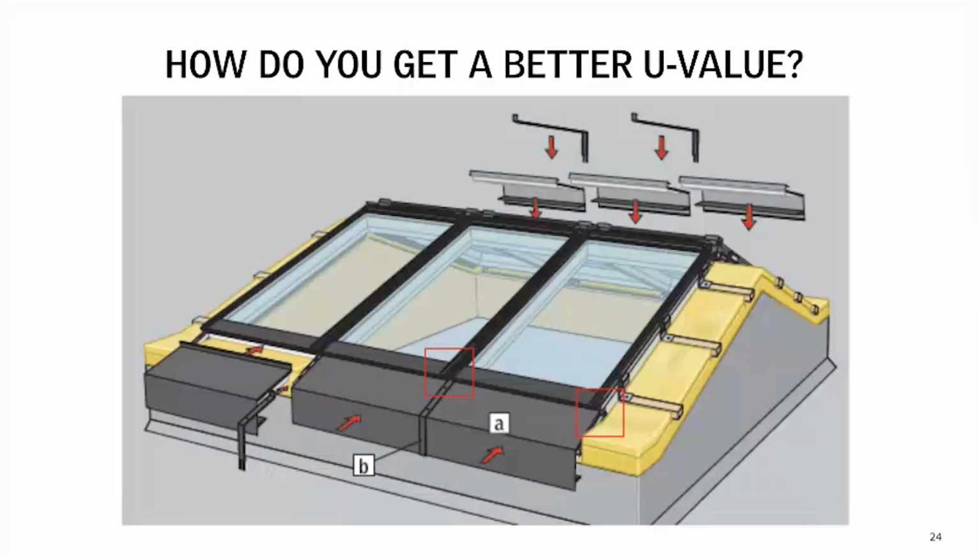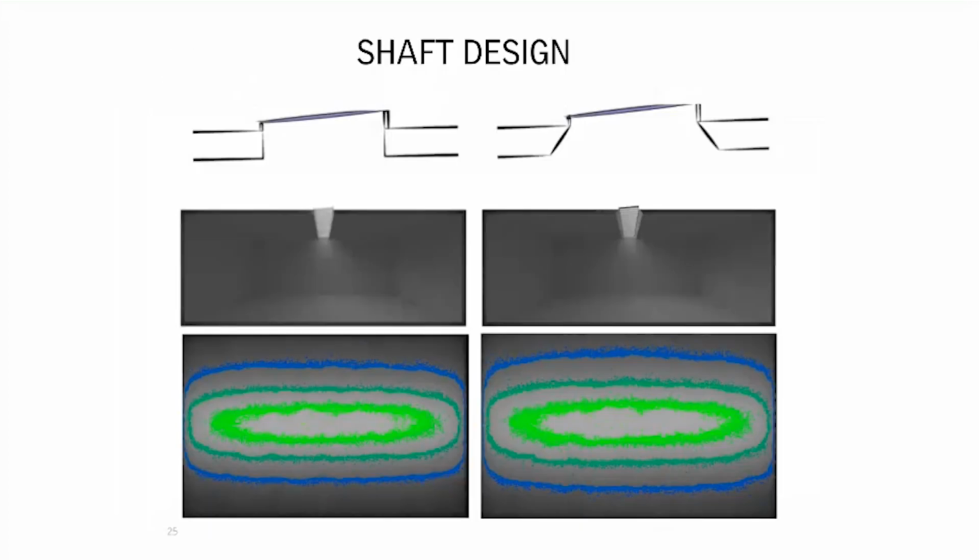Now, how you integrate into the building does not count as part of the U value, but when you're looking holistically at the energy performance of a building, you have to factor this in. Now, on sloped roofs, you could integrate the skylight or inset the skylight slightly into the roof. And we do this to some extent with some of our residential products going on sloped roofs. But if you're doing commercial projects and you're going to be operating on a flat roof, you likely have to lift your skylights up off the roof to get them out of the snow and watershed situation at that location. So you're going to have what we call a curb. A curb is the structure that the skylights are going to sit on. So to have a high performance system, we should be looking at how do we insulate that curb to make it better for energy efficiency.